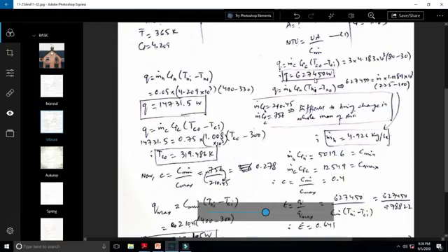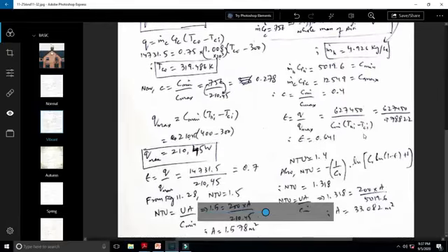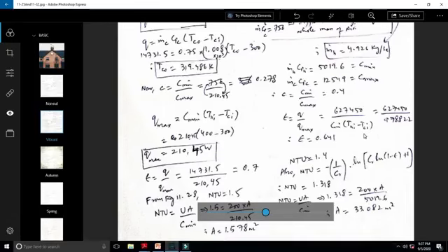And then the other thing is Qmax. Now, in order to find Qmax, we need to use this expression of Cmin times maximum delta T. And as discussed before, the maximum delta T would happen when we take the temperature difference of the maximum and the minimum value.